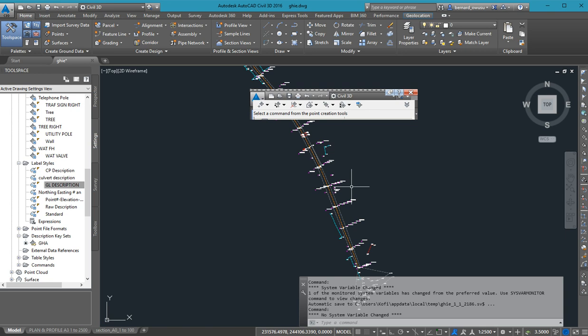For example, if you take a building, we may not be very sure where the target was placed. It could be that there was a foundation or something, so it was placed not on the ground, but maybe on the foundation. We may not be very sure where the target was positioned. Are we okay? If you take something like an electric pole, similarly, yes, it's from the ground, but we are not very sure where the surveyor positioned his target.